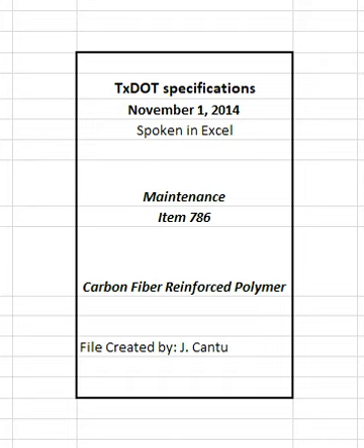Additionally, the engineer may request the presence of the manufacturer's representative for additional training if work personnel are not adequately following the manufacturer's installation directions. CFRP work will be delayed until personnel are trained and have demonstrated proper installation on an approved mock location at the contractor's expense.